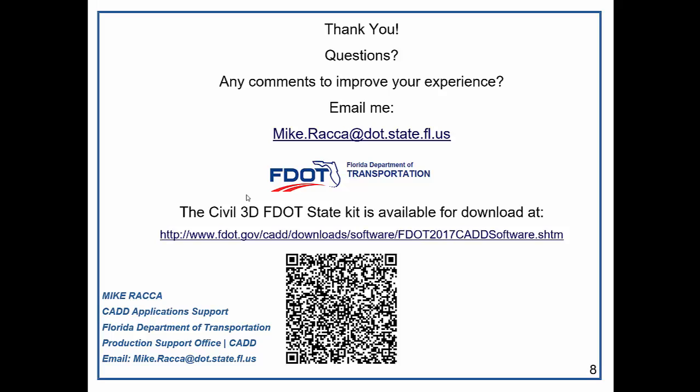Also, there's a link there provided to you to download the FDOT Civil 3D State Kit. It's free to download. The versions we are currently on is 2016, 2017. This is an add-on, so you must have Civil 3D currently installed before you can install one of the state kits, and the state kit year needs to correspond to the version of Civil 3D. So in other words, if you have Civil 3D 2017, you need to download our FDOT 2017 state kit.